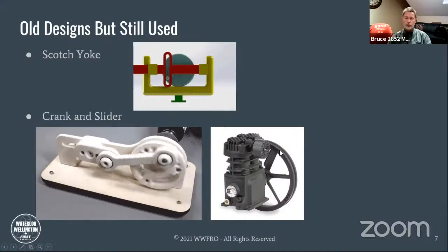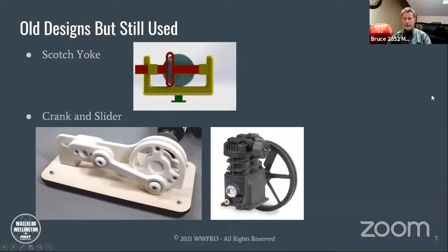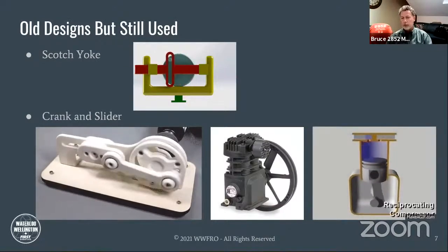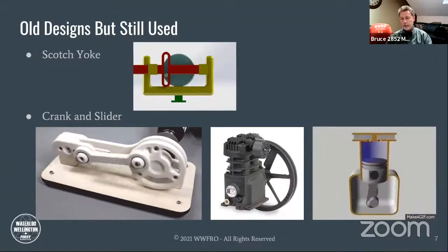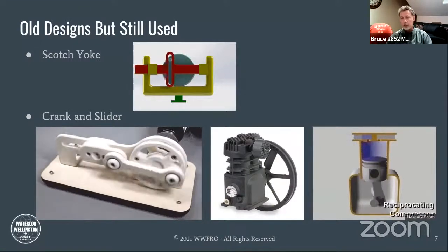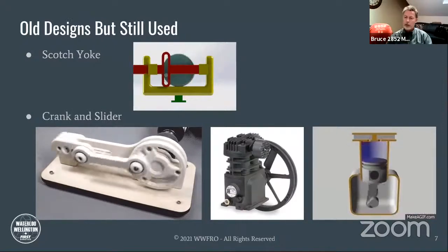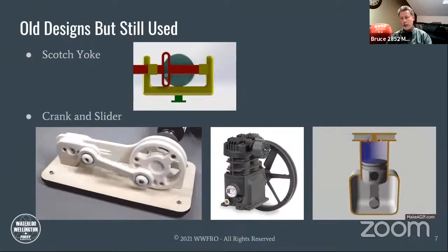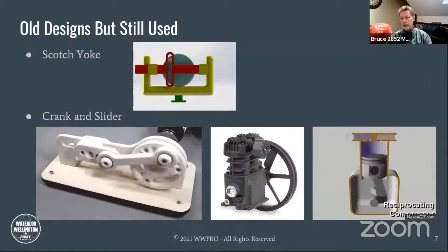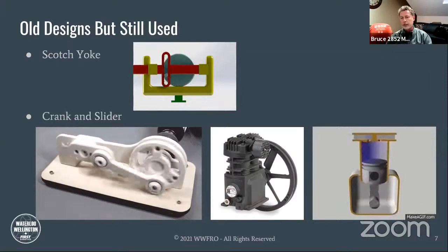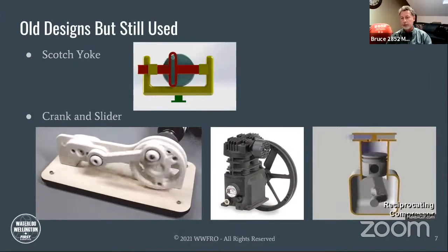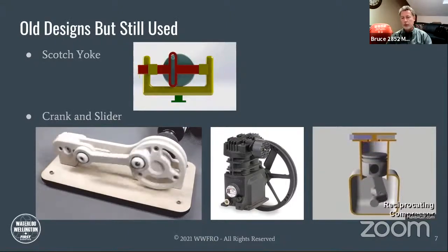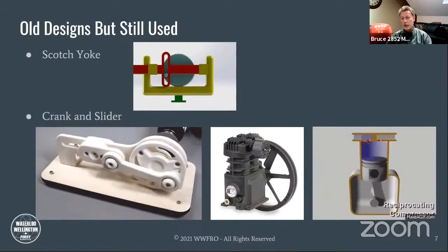So you have a rotary wheel, and then there's a mechanism inside. The mechanism looks a little bit like this. The wheel turns the crank. The crank is connected to a connecting rod, and it's driving a piston up and down in a cylinder. You can see it drawing the purple cool air in, compressing it, and pressing the red, high pressure air out. Once again, rotary motion causing a linear motion.